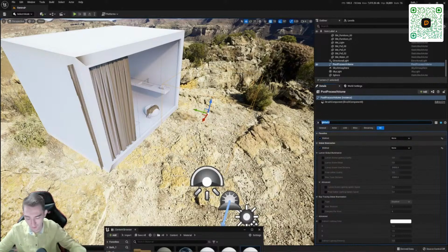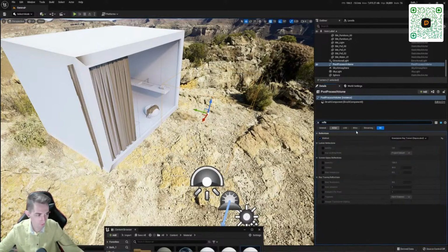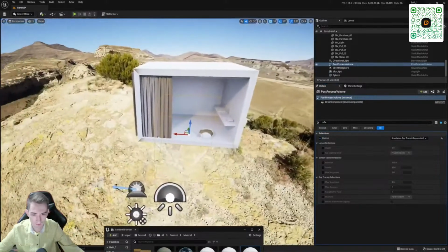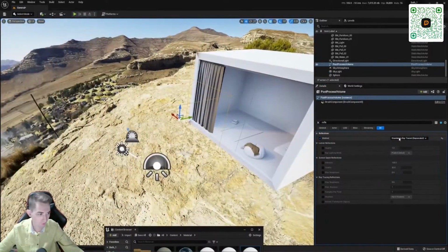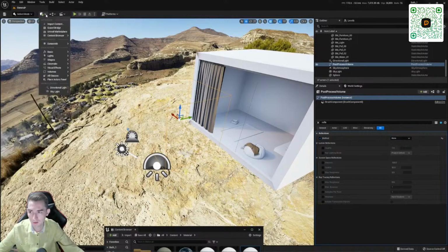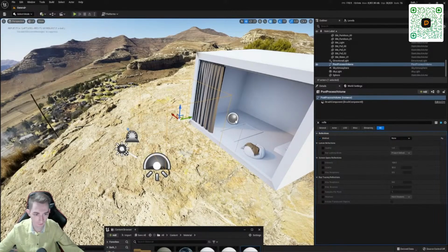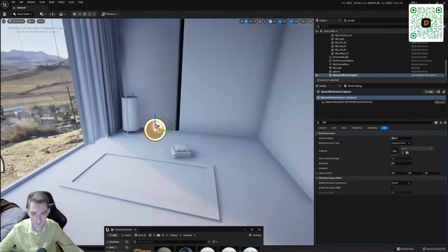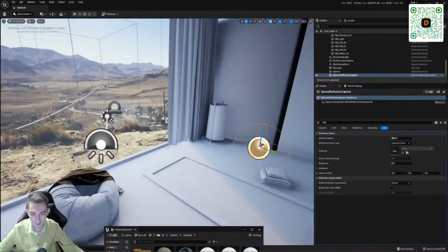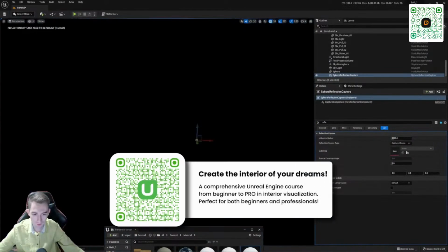Then I choose reflection, and here I choose Ray Tracing. Reflection with ray tracing is much better. You can use the None mode. If we use the None mode, then we can more accurately use the reflection sphere's effect in the future. That is, for reflection, we can use such elements that photograph everything around, let's say, and create a reflection due to this.